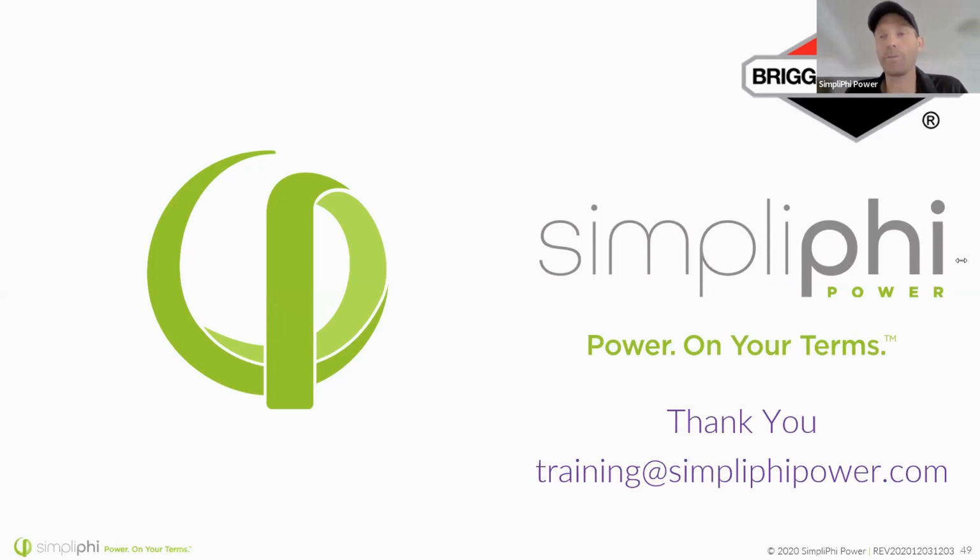It sends the state of charge information, sends the voltage, it sends the temperatures of the cells, which allow the inverter to calculate state of charge, right? Remember I said that state of charge, the voltage depends on the amperage out, as well as the temperature of the cells. And so if you want the inverter to properly understand the state of charge information, it sends all of that out as well. And so if you want accurate information out of your battery bank, a communicating battery would be the right thing to use. So hopefully I answered your question. I don't know about the virtual power plant part.